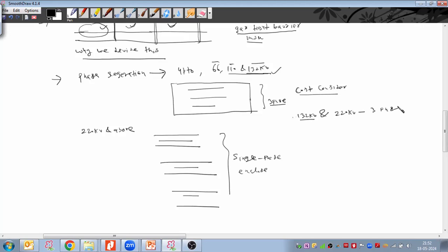Yes, right. Because normally 132 kV or 220 kV mainly goes to data centers or residential areas, where they require compact design. So the compact design helps them. Okay, and for 400 kV you propose the single phase, right? Single phase. Yeah, in any case, nobody has three phase in 400 kV and 765 kV.